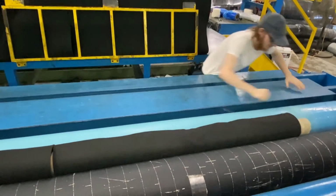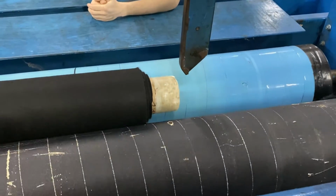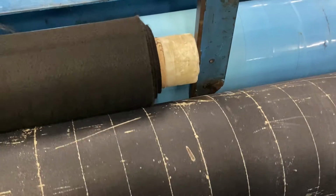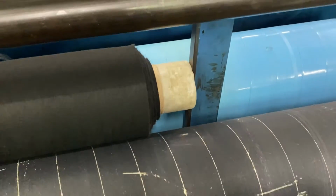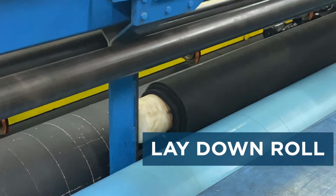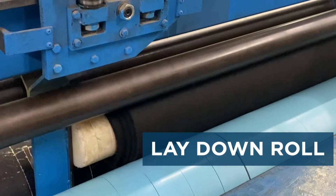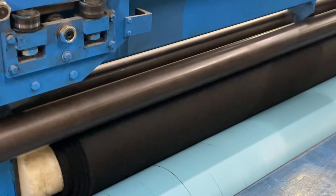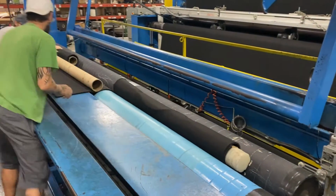Begin wrapping the core with the fabric in a rolling motion towards the middle of the pull and packing rolls. Once the core is secure in place, insert the core inserts in both ends of the core and begin to drop the core guides into place. The guides move up, down, in, out, and should be in position to rest on the core inserts before starting up the winder. The lay-down roller must also move down into place and rest on the core before starting the roll building process. The lay-down roll will aid in keeping the fabric in contact with the pull and packing rolls to make sure there is no slipping while trying to build a tight roll build.